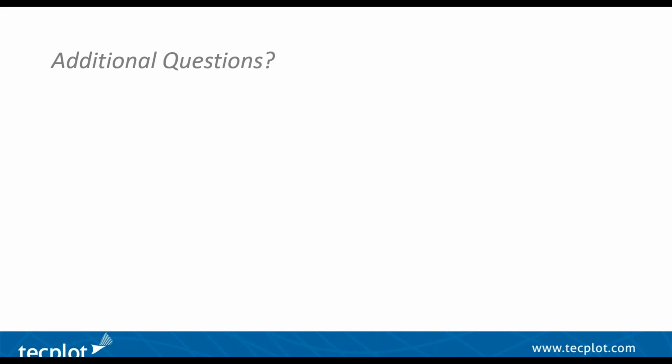So there's two different ways. You can use data alter if you know the equations directly. This would be found on the data command. You can go to create, specify equations and type in equations using variables already existing.